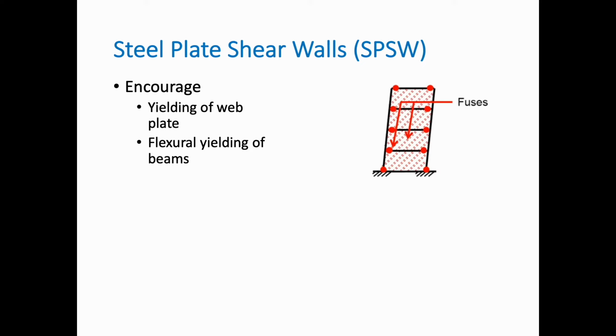It's sort of like an infill wall of a steel plate with perforations or without, and that is providing some inelastic capacity, and we're expecting that the plates will yield at some point to dissipate that energy and provide the required ductility.